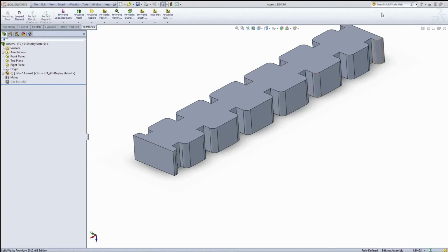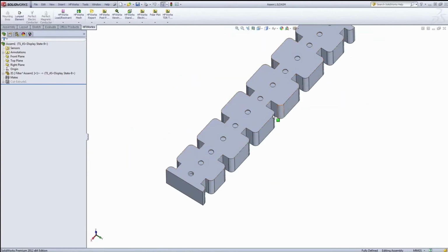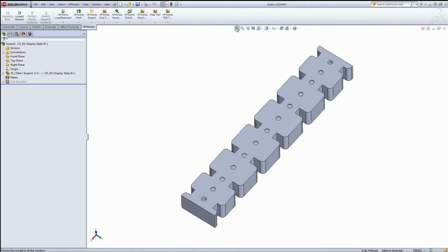So what I'm showing here is a multi-cavity filter with what we refer to as tuning screws. This is one of many applications. Obviously, the software is general purpose. It's based on the finite element technique, so it's not limited to any given structure or any given set of materials. Whatever you can draw and model, and you know what materials are used, you can simulate, analyze and get data for. So the filter is just one example.